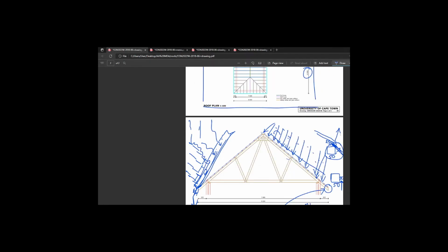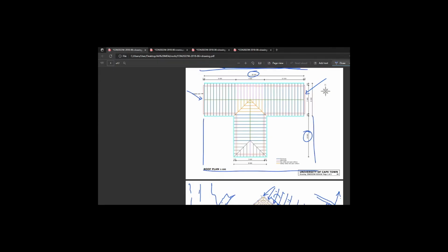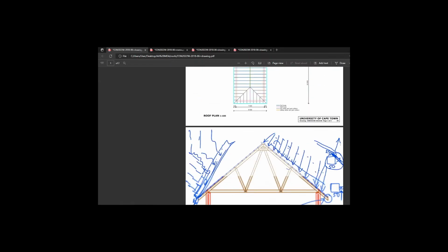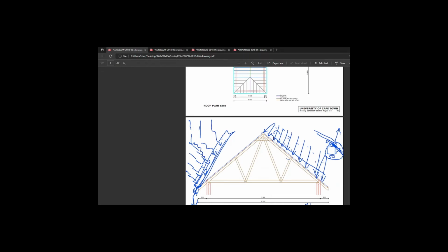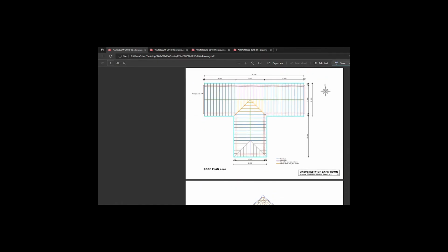Let's go here. Okay. Flashings apply where we have roofing meeting brickwork. That's typically a gable end. I need to correct myself. Not necessarily just a gable end. It is a gable end with a parapet wall, because you can have a gable end with a barge wall, and in that case you would not have flashing, right? Right or wrong, correct me if I'm wrong.